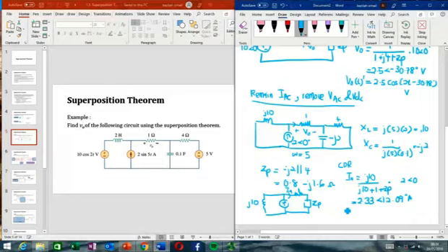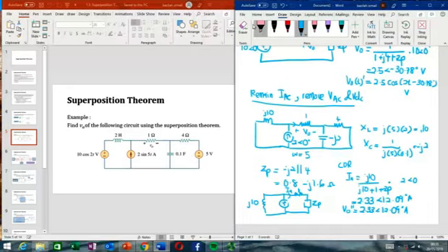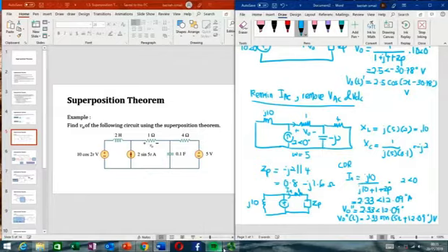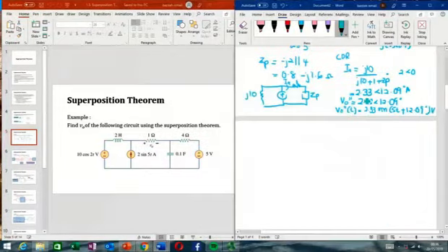Okay, and we can calculate V0 by multiplying the current with the resistor. Since the resistor is 1, we will get the same value. Sorry, the unit should be volts. Okay, so lastly convert this into the time domain. So the answer is 2.33 sine(5t plus 12.09) volts. Okay, next calculate VDC. So remain VDC.